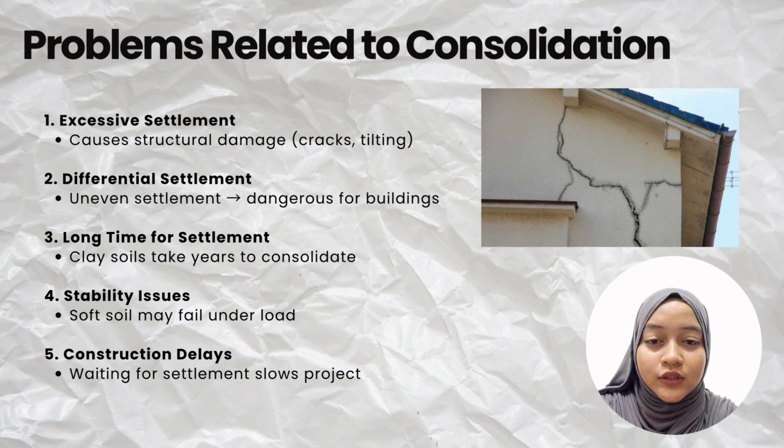Now I want to continue about problems related to consolidation. The first is excessive settlement. Excessive soil settlement can cause structural damage, such as cracks and tilting of buildings. The second is differential settlement. Uneven settlement between parts of a structure creates unequal stress and can lead to structural failure.